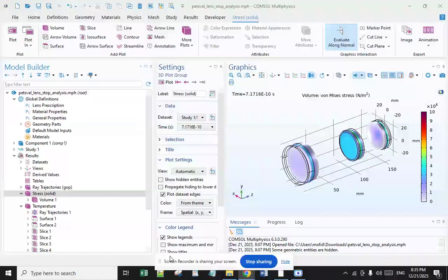To simulate the image the sensor would see in this scenario, STK's electro-optical infrared synthetic scene generation tool is employed. This tool takes into account the spatial, spectral, optical, and radiometric properties of the sensor, target, and any atmospheric model employed to generate a physics-accurate view of what our sensor would see if it were launched tomorrow and we were to download an image from a pass over either city target.